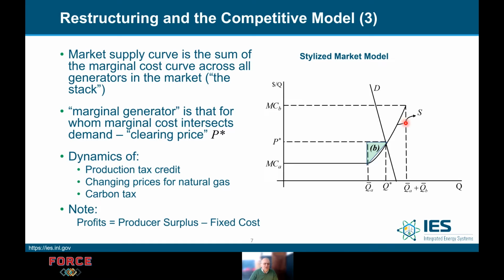But before we get into that, there's some terminology that I'd like to identify here. The grid operator looks to see where their forecasted demand, or their forecasted load, intersects with their supply curve, and then the entity whose bid intersects the demand curve becomes what we call the marginal generator, or in other words, this is the clearing price that enters the market. We typically refer to those in our industry as the locational marginal prices. So that's where they come from. And as has been mentioned in our modeling exercises, this is happening at every moment of the day.